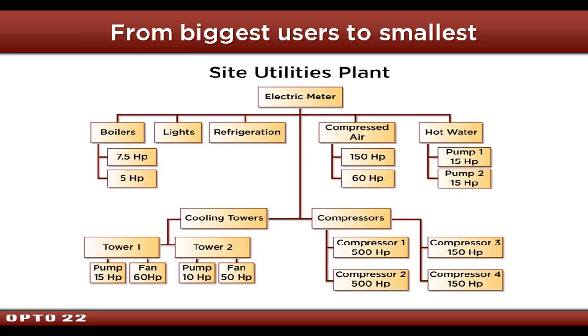So, but don't waste time. People go in and they tend to waste time on small systems. We went into a meatpacking plant. I'll talk a little bit about that. But they were using 5 times the amount of energy that they should, and it was in the refrigeration system, and they'd had an audit by the utility, and the company that did the audit recommended new lights in the office. They missed the fact that the overall facility was using 5 times the amount of energy it should for the amount of process that they had there.